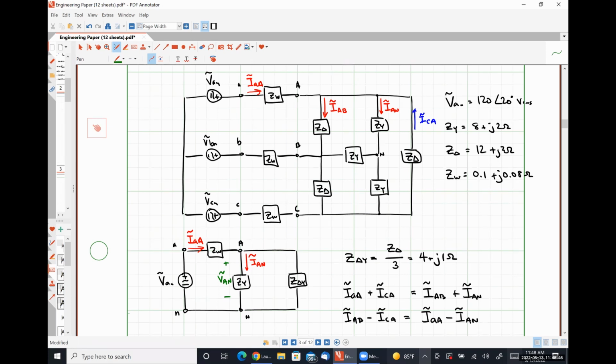So if I had done IAC here, it wouldn't be as immediately obvious what the phase shift would be, because it would be a negative 240-degree phase shift, but then I'd also have to multiply by an extra factor of -1 in there. Exactly right. Yeah, you go AB to BC to CA and then cycle back through them over and over again.